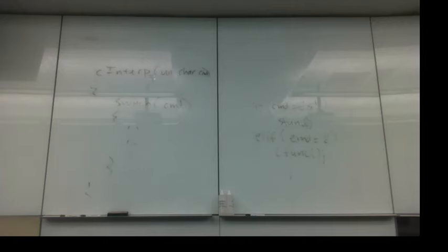Do you remember, did you look at the peripheral pin select at all? Connecting the peripheral to a certain pin? Yeah, it's kind of complicated. But basically you need to set up the peripheral pin select register too. It's just like the tri-state register, except it just connects a certain peripheral to a certain pin. So that would be step 2, maybe.